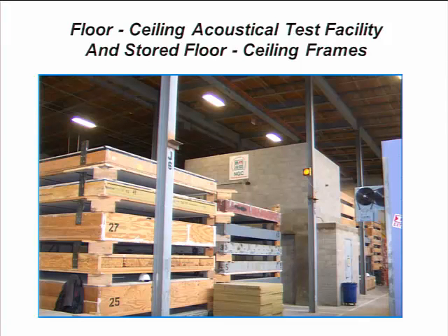One thing I want to point out is that the IIC test, the SDC test, does not have a standard assembly in the specification, in the test E90 and E492 ASTM specification. E2179, which is Delta IIC, is the only one that has a standard assembly, and that's a 6-inch slab.